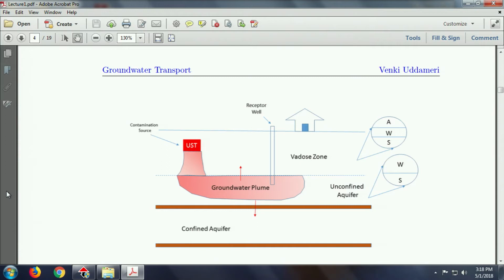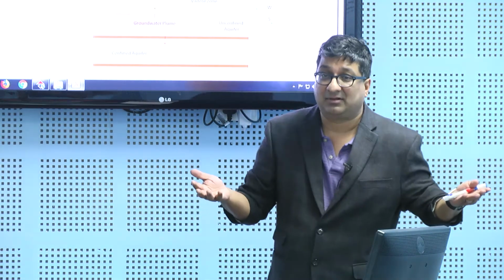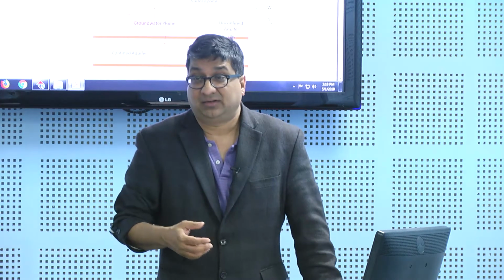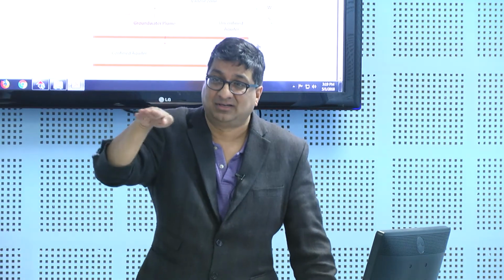So the key challenge of in situ groundwater remediation is not being able to get to the chemical. If you can get to the chemical, we have all the technology in the world to treat our problems. But the key challenge in groundwater is getting to that chemical, a risky proposition a lot of times. There is a certain probability that we may never hit that chemical with the technology we are using. This is where nanomaterials or nanotechnologies are becoming very popular because they are very, very small. They'll go into smaller pores because there is nothing bigger than their size, so they can go somewhere and clean up things.